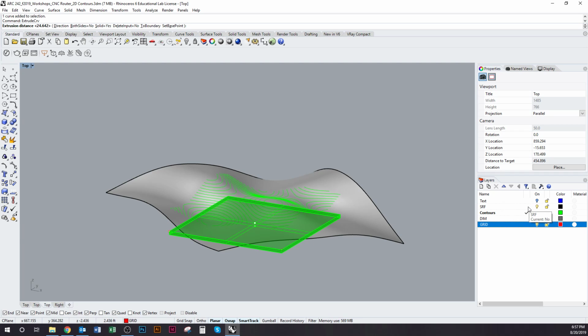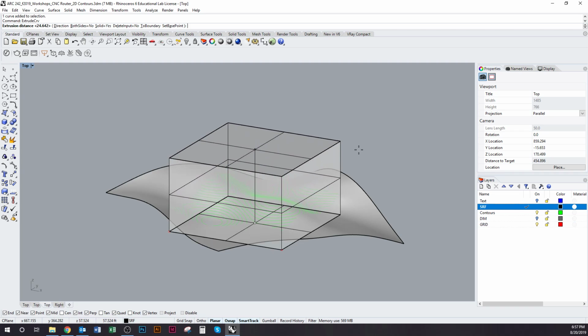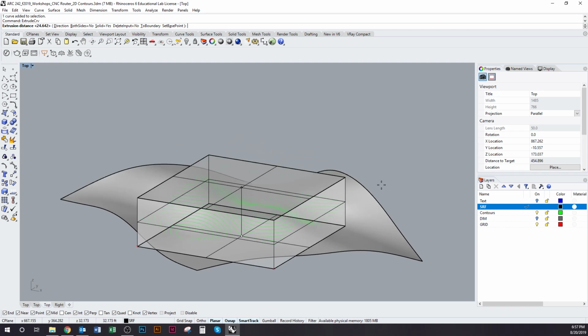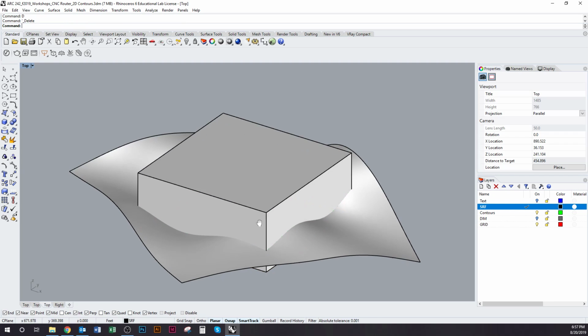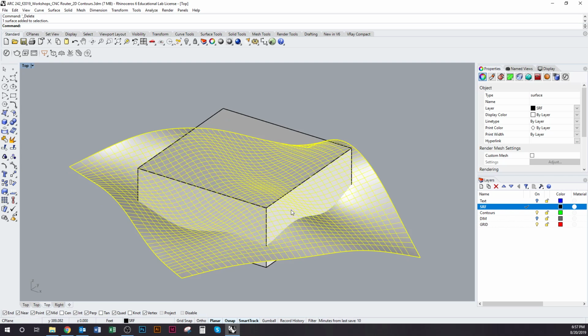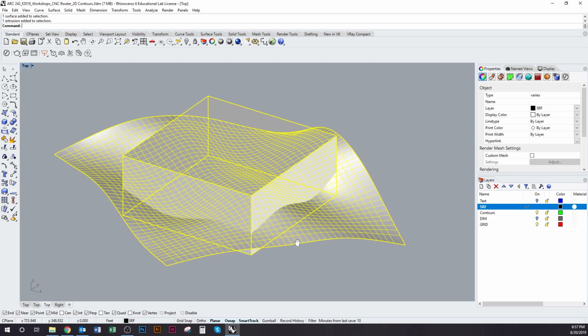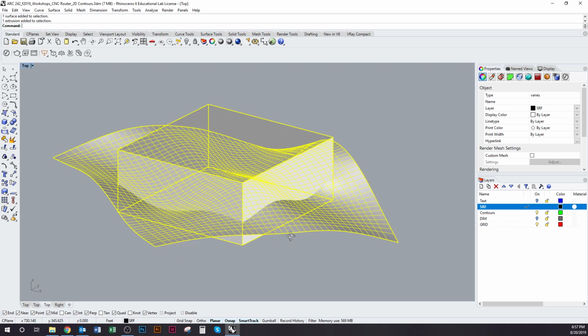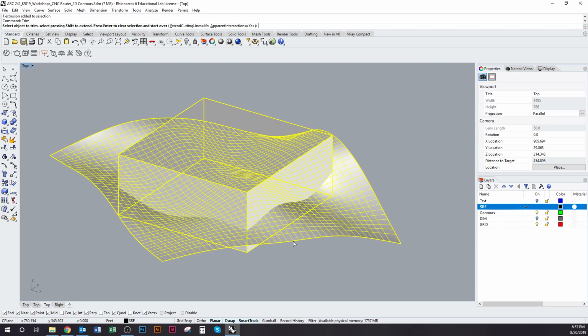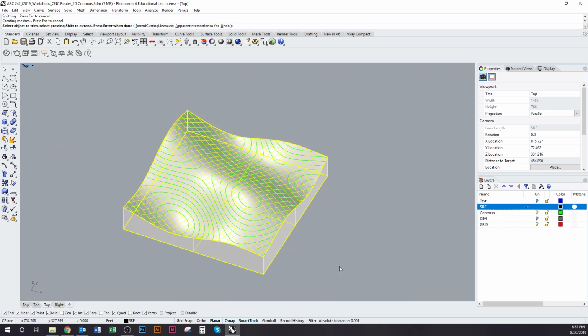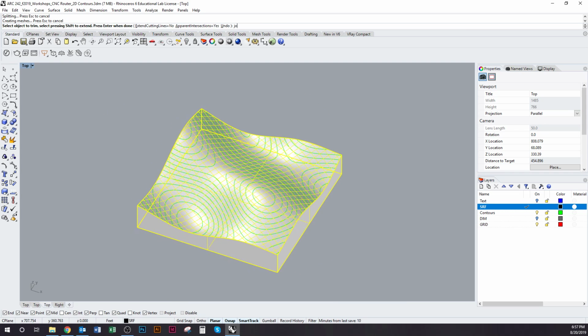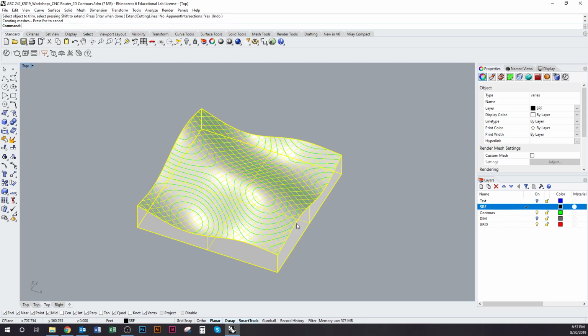And I'll just change my current layer to the surface layer. Doesn't matter if it's closed or open, I just want to extrude it all the way through that surface. I can delete the curve, and then I'm going to go ahead and trim these two objects and join them together. So if I select both at the same time, type trim, I can trim the box, I can trim the excess topography, and then when I'm done I'll just press enter to finish the trim command, then press join.